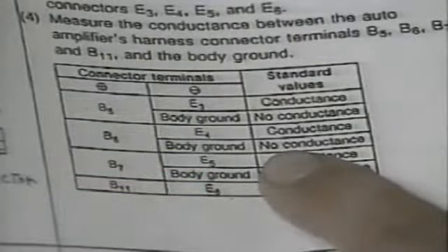If the readings are correct, proceed to the motor harness check. Check for continuity between the actuator connector and the ECU connector terminals as indicated in the service manual. If the readings are not correct, the harness is at fault. If the readings are correct, the actuator is at fault. The intake actuator chart is not divided because this actuator uses position sensing contacts.